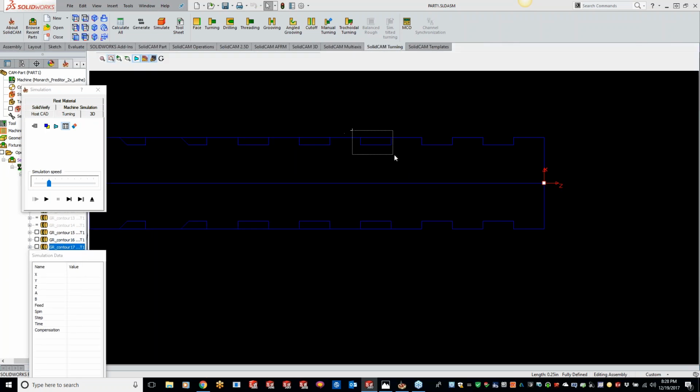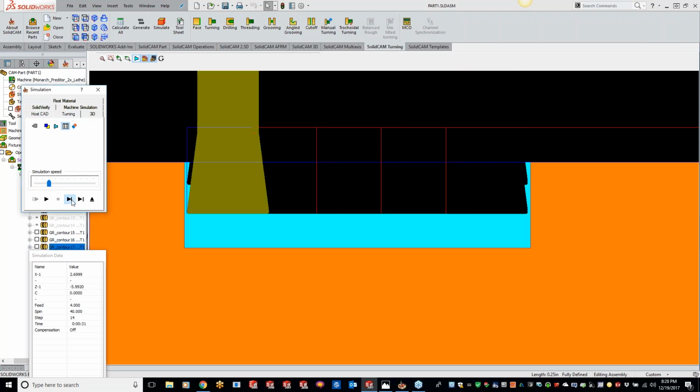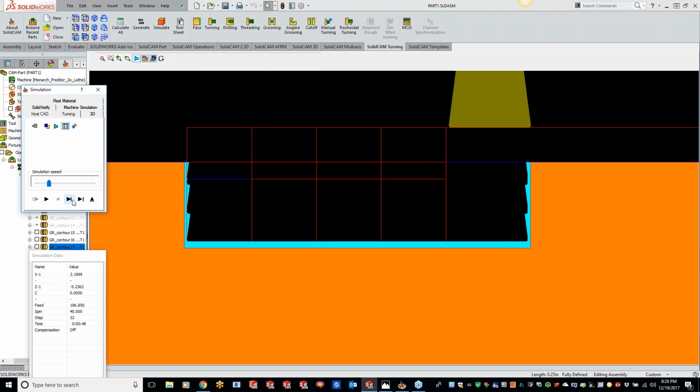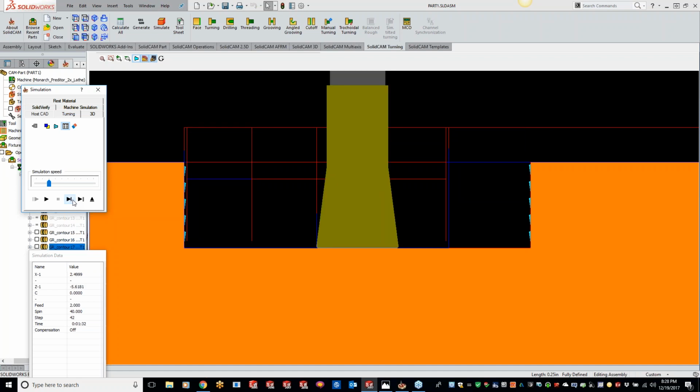It all depends on kind of how the geometry is set up for it. So go down, over halfway, go down, over halfway, clean it up. So kind of utilizing both sides of the inserts for you guys. More than anything, just kind of pushing down on those sides instead of kind of doing that side cutting as it was coming up like what we did with the ISO turn.